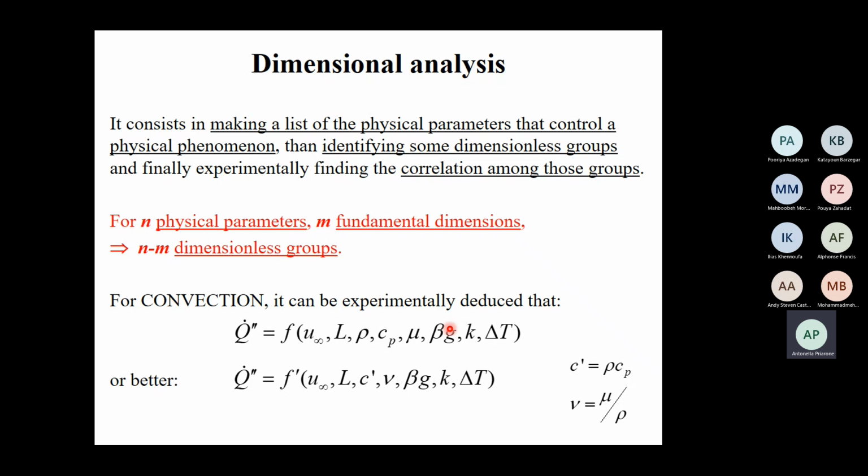So higher temperature means lower density. In a gravitational field, that zone of fluid with lower density rises up, and other zones go down, with the creation of the convection movement. This type of behavior is called buoyancy forces. Beta g is a manner to quantify the buoyancy forces that are important when I speak about natural convection.